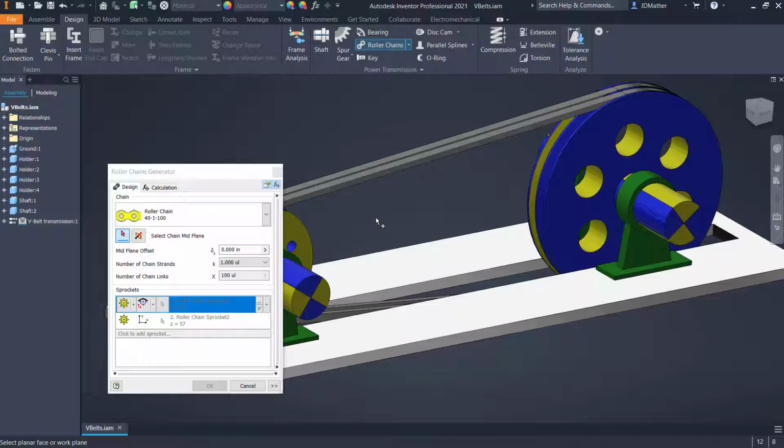One question that always comes up is somebody wants to do a real chain. When doing a chain, I would use one of 2 visual tricks. I would either just put a cosmetic texture that looks like a chain, or I would do a trick with an optical illusion where only one real link is moving, but it appears via an optical illusion that the entire chain is moving. If you try to put in the number of joints or constraints that would be required for a long chain, that will bring the software to its knees. So in a later lab I may show you how to do a chain.